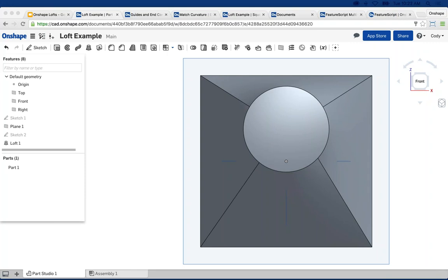I tried doing a circle to square loft where the two faces are 90 degrees to one another and an offset. When you do something with 90 degrees, it's important to keep in mind it's going directly from one to another. So it may be worth considering creating one intermediate plane halfway through and constructing the transition between the two there.